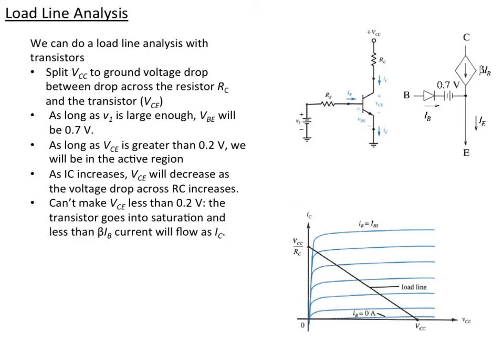And so what happens is that we put a voltage in on the base. That voltage creates a current that flows through RB. Enough current flows that we reduce the voltage here, but as long as the voltage here is 0.7 volts above the emitter voltage, current will flow there, and a much larger current will flow here.